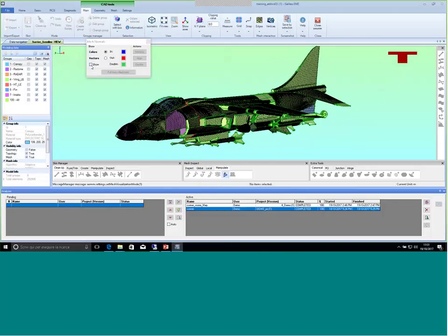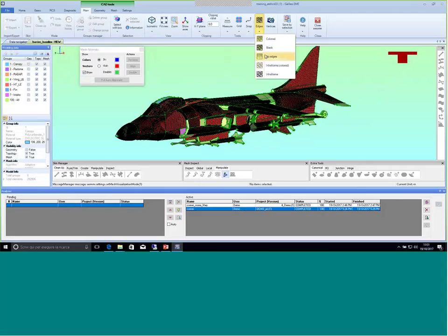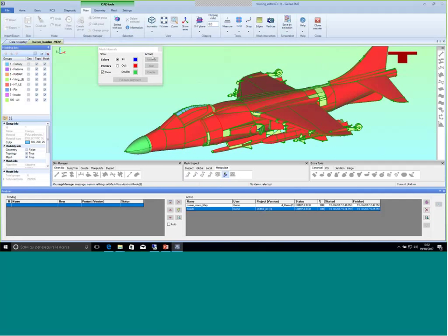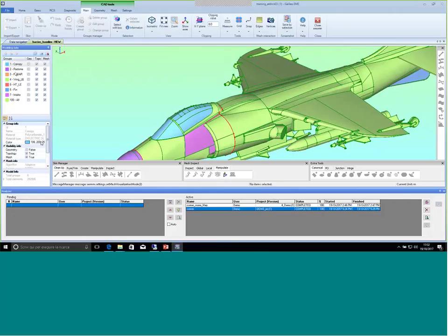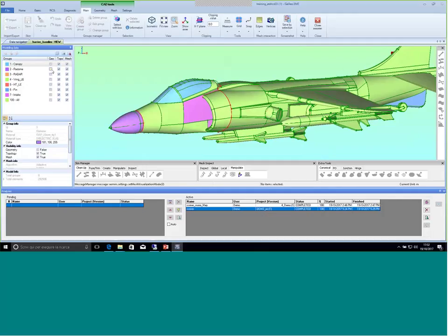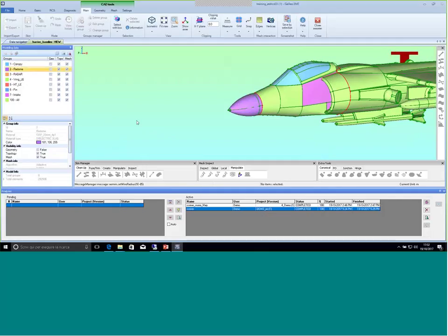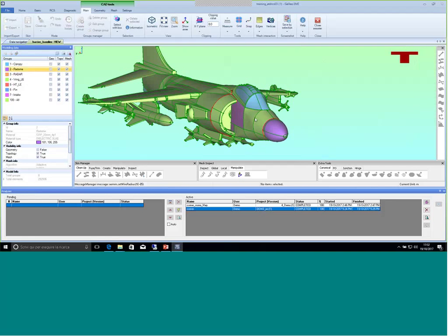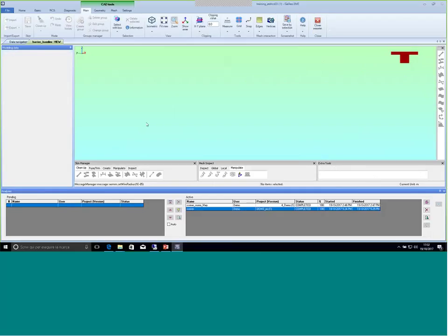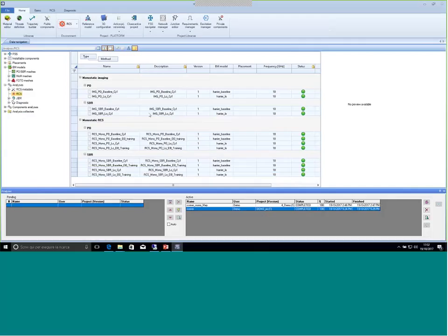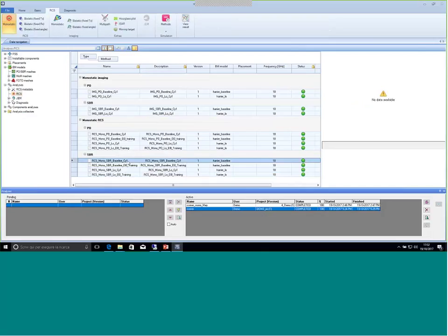Here, for example, the model is basically made by PEC, but the canopy is made by a polycarbonate material, a dielectric slab. The radome is dielectric as well. And the cavities here are made by PEC. So I run the first RCS simulation for this target. This is the baseline configuration, for example, with the SBR.